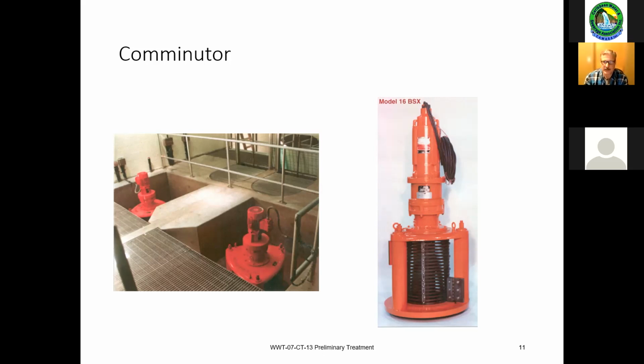You're taking pieces of rag, and instead of catching them in a bar screen or a plate screen type scenario and removing them, you're actually making them smaller so they can flow through. They will wind up wrapping around all kinds of pieces of equipment in your plant. The incredible reforming rag, it's amazing. Aeration systems are famous for having rags reformed in them.